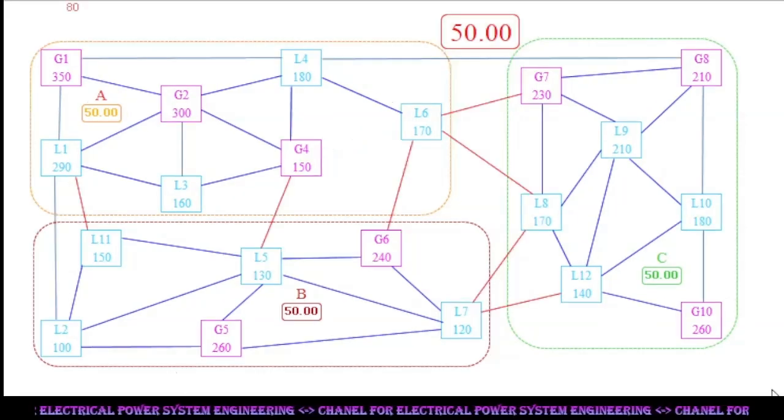Now all the three systems are interconnected. Red lines are interconnecting tie lines. Red bold box indicates grid frequency, which is common for all three power systems. Now individual system frequency is meaningless. However, its display continued for comparison of isolated system frequency with grid frequency to observe the difference with grid system.